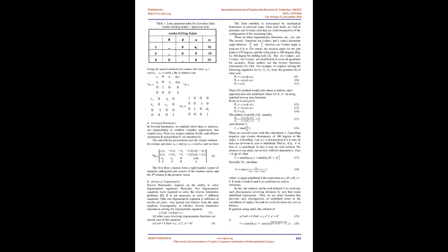For example, in the case of a 6-link robot with the first 3 links creating the arm, we will first solve the arm before we go into the full-scale 6 links. For the sake of completeness, we include the robot Fig 2, the link parameter table Table 1, and the A matrices. For example, a jumbo drilling robot is displayed here in Fig 2. The figure has clearly marked joint axes and link parameters. One may flatten the robot, see Fig 3, to set it in the rest position for ease in creating the link parameter Table 1.